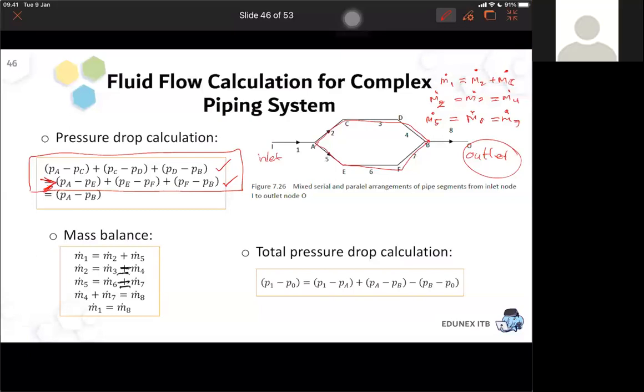It will go down, sir. Are you sure? Oh, wait. To the top, sir? Why? Because the pressure drop is greater. Yes. If the pressure drop of the top line is higher, it means at point B from the top, the pressure will be lower than point B from the bottom, right?